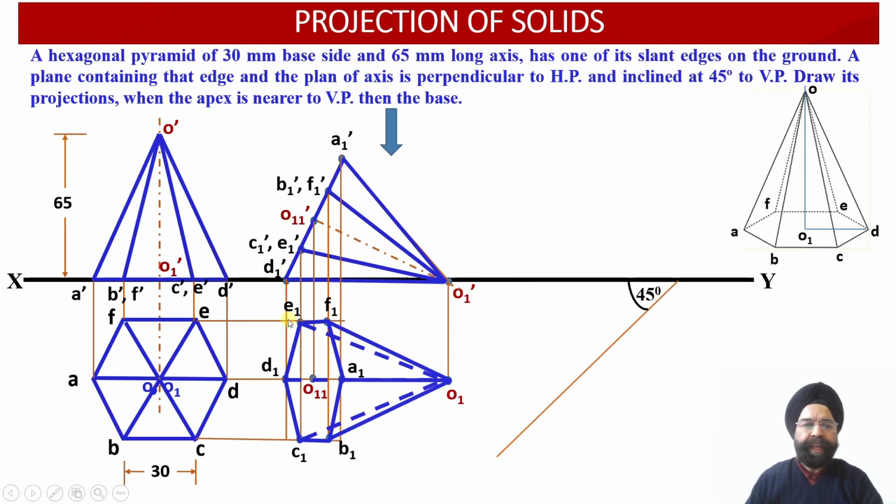Now we observe over here that this hexagonal construction has been inscribed into this rectangle. This rectangle we are going to draw at this particular position. The hexagonal construction will be made over here, while the apex has to be located over here. Now we can check, this is the rectangular construction which we have made corresponding to this hexagonal projection which we have obtained in the top view projection over here.